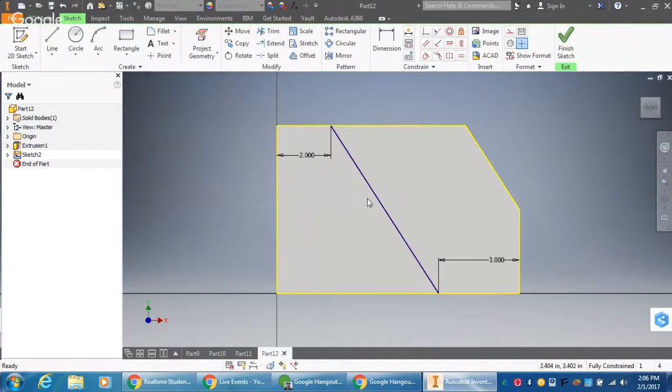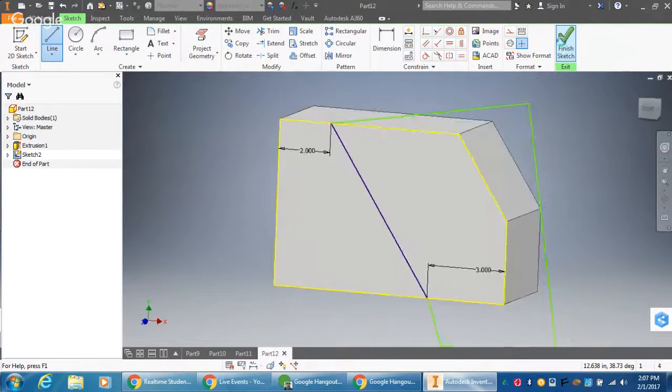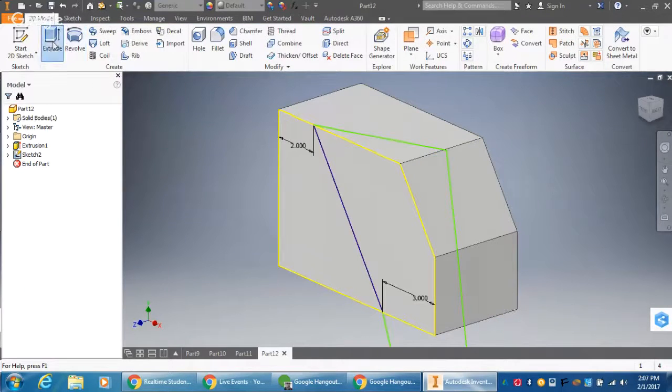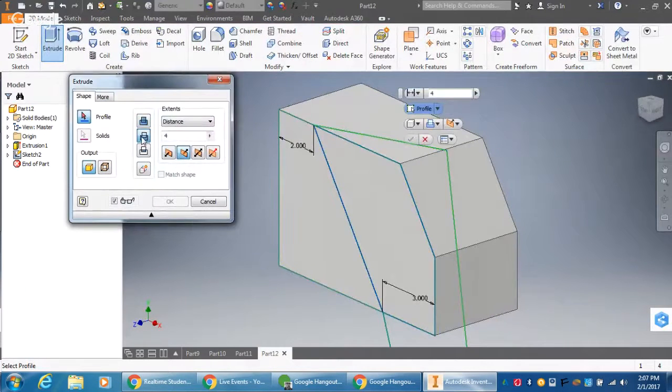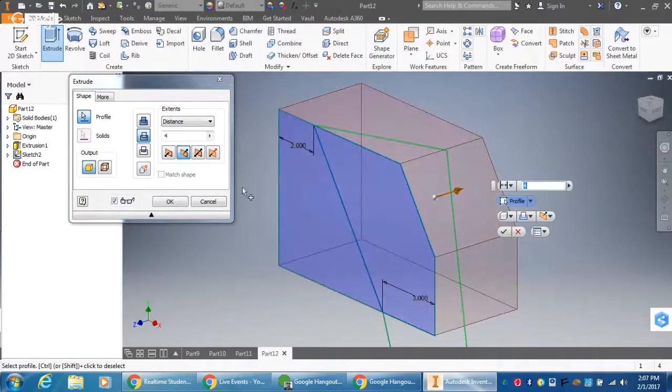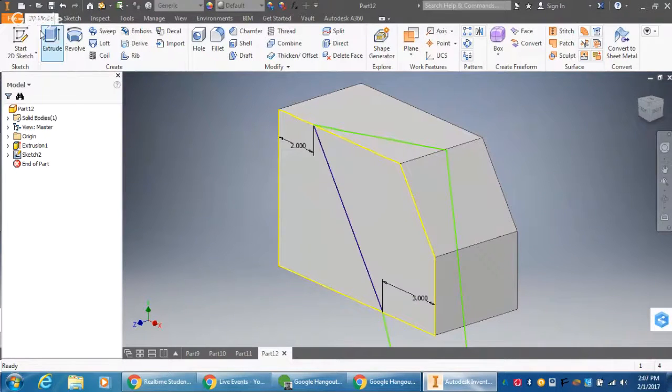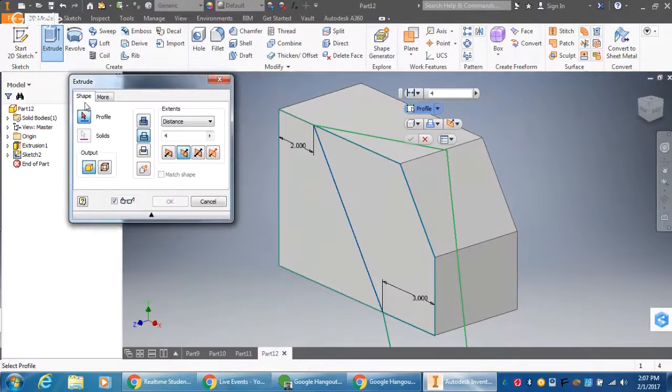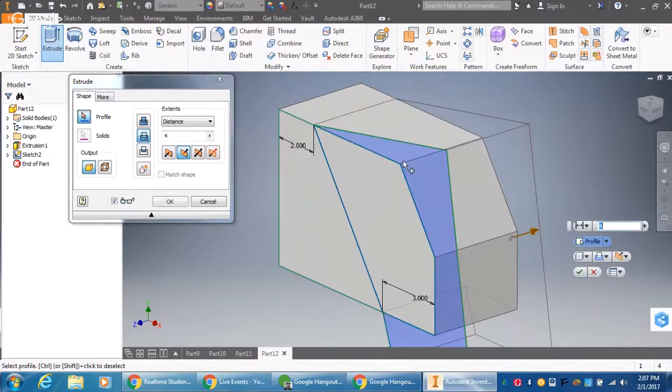And I knew that ahead of time because generally if you have closed geometry, it turns blue like that, or whatever your color scheme is. In my color scheme, it turns blue. But I'll just use this point to show you something else. Since I'm cutting, I really don't care how much I cut, to be honest. I'm just going to cut this and make sure I have closed geometry. Why? Watch this. I'm still going to extrude. I'm going to cut. Hey, extrude. Cut. Select your profile.